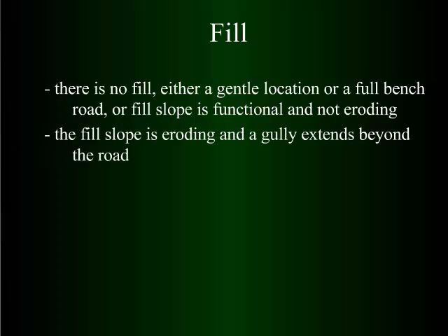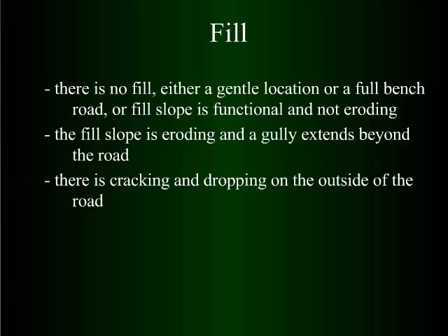Looking for the gullies coming off your fill slope that might extend down the hill and end up entering streams. Sometimes, if this is about ready to fail, if it's got too much water in it, you'll start seeing tension cracks. A lot of times they'll be right where it separates from the native grade. But sometimes, if the running surface is compacted enough, the tension cracks will be right on the edge of that. If you start seeing tension cracks, you've probably got a slope or a fill stability issue.